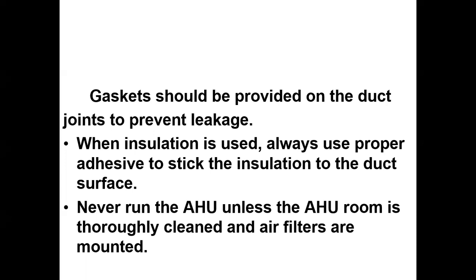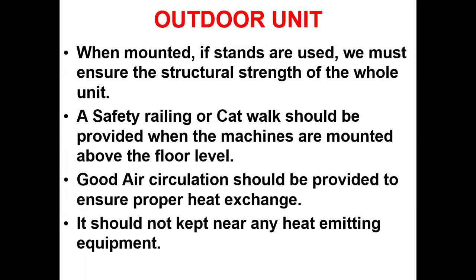Otherwise, what will happen? The dust particles will form right onto the cooling coils, and eventually it can create some issue with the contact factor, the amount of air getting contacted with the cooling coil. All right.